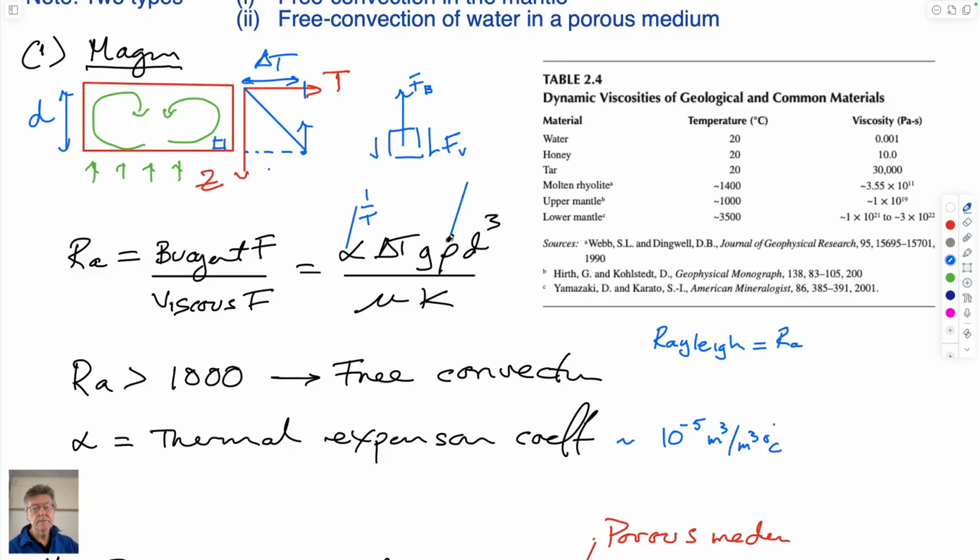So this is density, and this is the depth. So this is the height of the convection cell. And as I said before, roughly these will develop so that they're more or less equiaxed. By moving, it will set up its own pattern. That pattern can switch with time, but roughly they'll be equiaxed, defined by this geometry. This is the viscosity of the fluid.